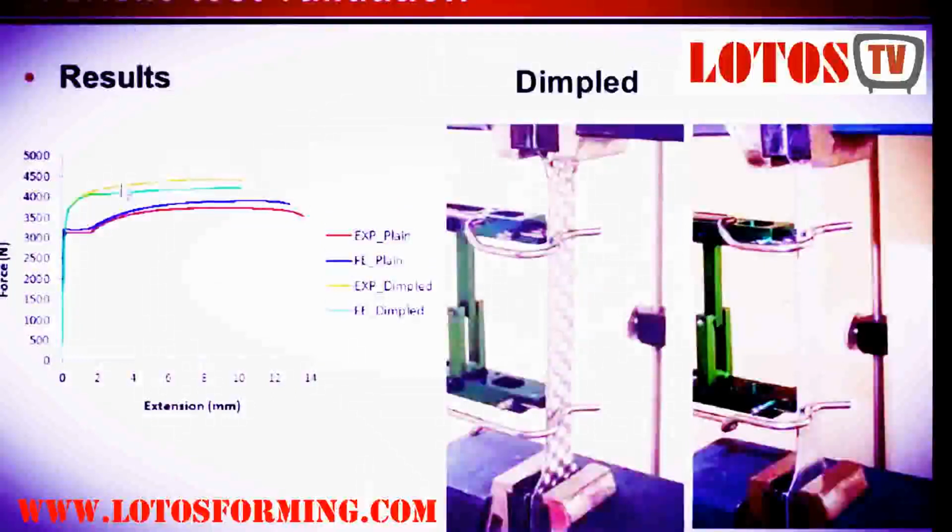So if we look at the result we obtain on the left side, we can have a comparison between simulation and the test. The first two curves, the red and the blue, are the result of the simulation and the test for the plain strip. And then the green and the orange are the result for the simulation and the test for the dimple strip. And we can see a very good correlation between the simulation and the test, with the maximum difference between them less than 4%.